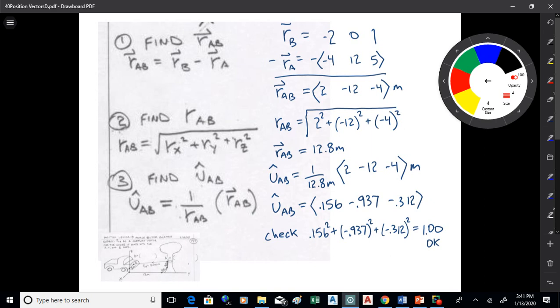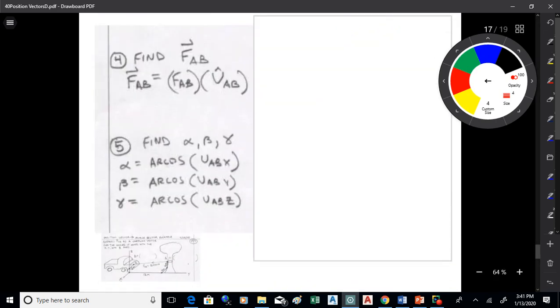All right. Now, if I want a force vector, what's the next thing I do here? Scale it up by what? By 8,000, okay? And see, that'll keep the vector pointing the same direction, but now it'll have a magnitude of 8,000. So what I'm doing there is I'm taking the length of the vector out as a magnitude and replacing it with the magnitude of the force. And that ends up getting me a force vector that points in the proper direction, okay?